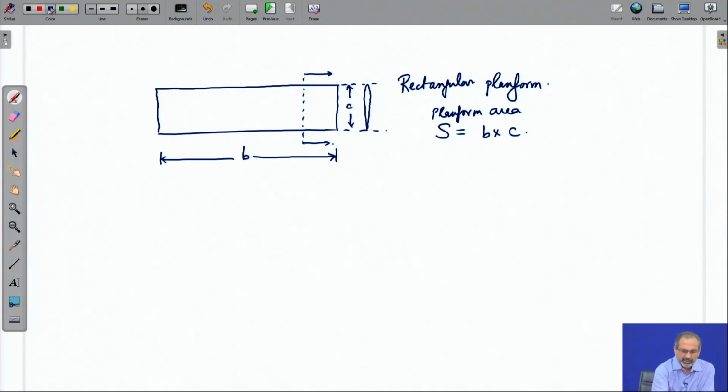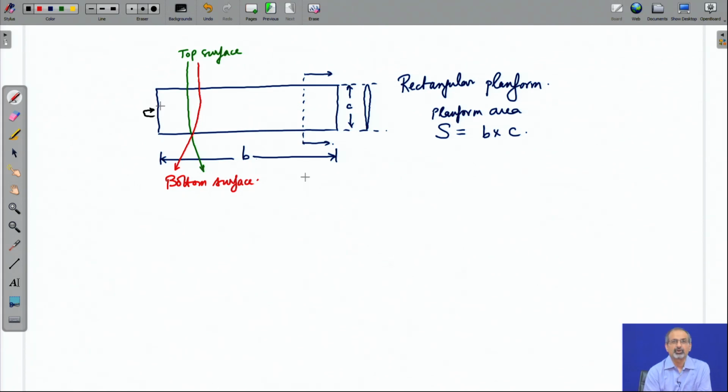How would the flow behave as it moves past the wing? The flow on the top surface would turn this way as it moves past the wing. The flow at the bottom surface would turn the other way. Why is it this way? Remember that it is all due to the effect of the curling up of the flow from bottom to top, that is turning the streamlines.